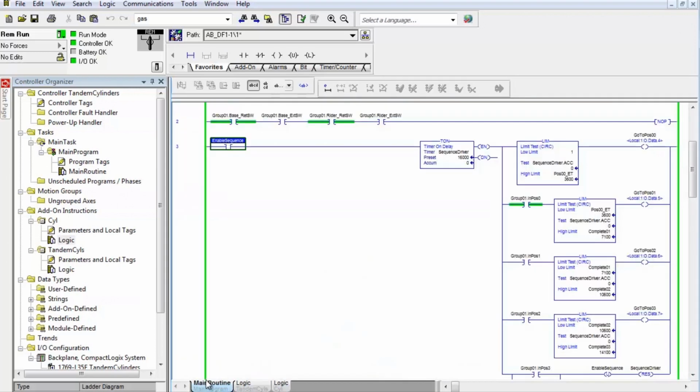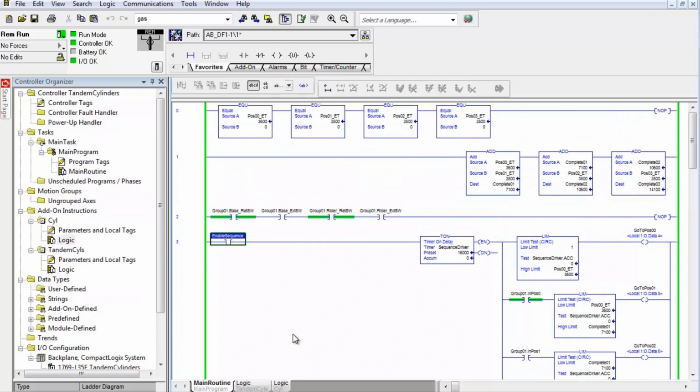So the only way that we can really extend out is we would have to change these to give us more time. But remember, if we take more than 75% of 3 seconds, which is what our extending and retracting timers are set at, so both switches are retracted, meaning that our cylinders are both retracted, so we're in position 0. If you look at the graphic in your manual, you'll see that if data point 0 is on and data point 2 is on, then you are in position 0.